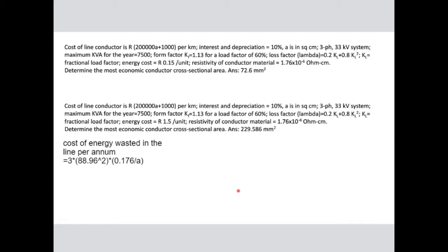That okay? Then time is 8760 hours, but we said that there is loss factor. Loss factor was 0.408. Remember that lambda will come here, 0.408. So that's that, and then you multiply it. I just unclicked it, so now it's not allowing me to type there anymore. It has to be now multiplied by 10 to the power minus 3.